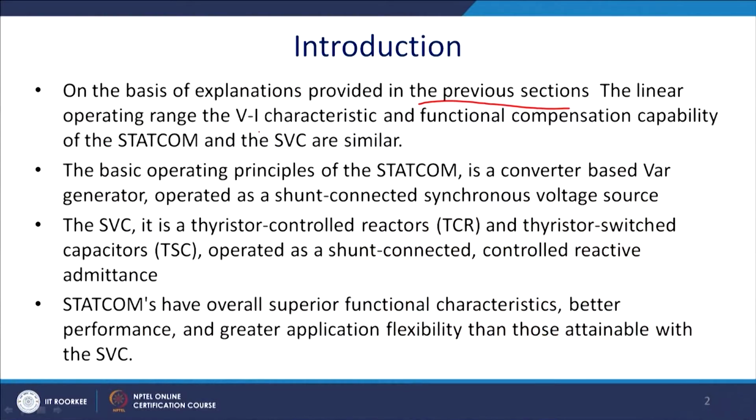On the basis of the explanations provided by the various sections that we have already discussed, the linear operating range of the VI characteristics and the functional compensation capability of the STATCOM and SVC are similar.